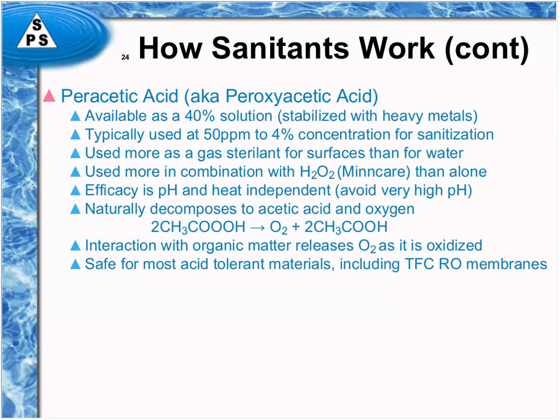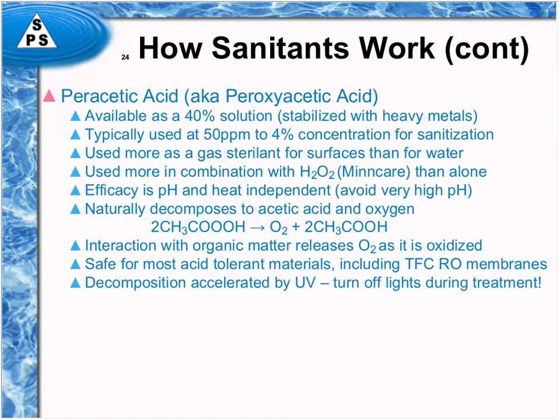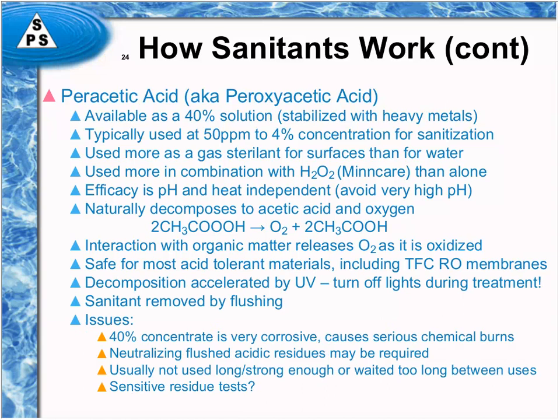It is safe for most acid-tolerant materials, and that includes the thin-film composite RO membranes. So it can be used at effective concentrations in RO membranes as a sanitizer. The decomposition is accelerated by UV, just like with hydrogen peroxide. You need to turn the light off, and you do remove it by flushing, and it has similar issues to hydrogen peroxide relative to its corrosiveness, as well as, in this particular case, if you do flush it directly out of the system, you may need to be neutralizing the residues before it goes to the sewer.